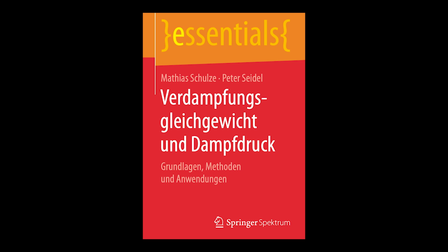That's a perfect microcosm of the technology. They typically use sodium acetate trihydrate. You heat the material until it melts, absorbing and storing latent heat. When you initiate crystallization by clicking the disk, that stored energy is released over a longer period, providing steady warmth without the temperature immediately skyrocketing and then dropping. It's just a really clever way to manage energy flow. Very effectively and consistently, yes.